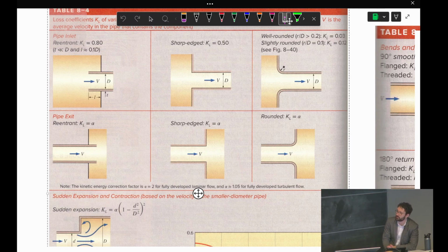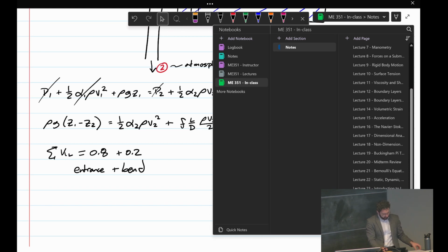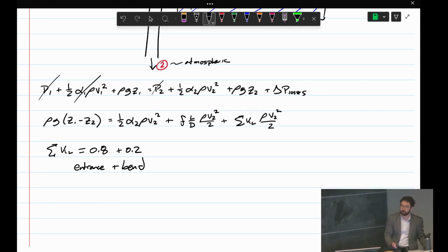Okay. So if we were trying to pump into, say, the bottom of a tank, then we would have something like this, where you have a reentrant type loss or one of these edge losses. That's a good question. Any other questions on the minor losses? Yep. If the end of the siphon was at a fixed position and the water level rose at a certain point, you would have to account for it feeding back into a tank. Yeah, then you would have an entrance loss. The reason that I'm discharging to the atmosphere there is to make my assumptions much easier. The siphon will still work if I discharge back into a tank, because there's still a hydrostatic difference. But I just want to make the assumptions easier, basically.